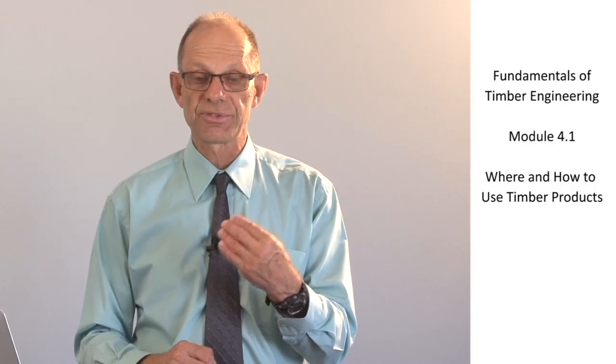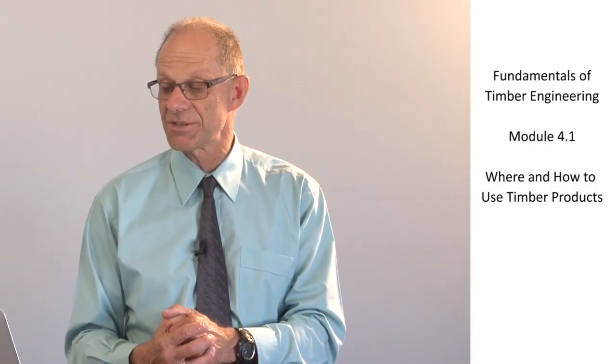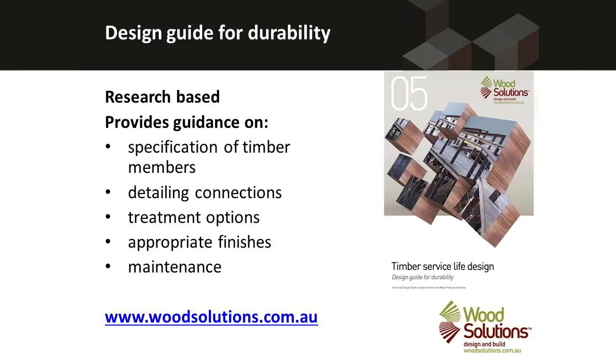The life of timber in service can be assessed by looking at a design guide for durability. There is one such design on the web, WoodSolutions.com.au, and I will extract a couple of captures from that to show you the way it works.